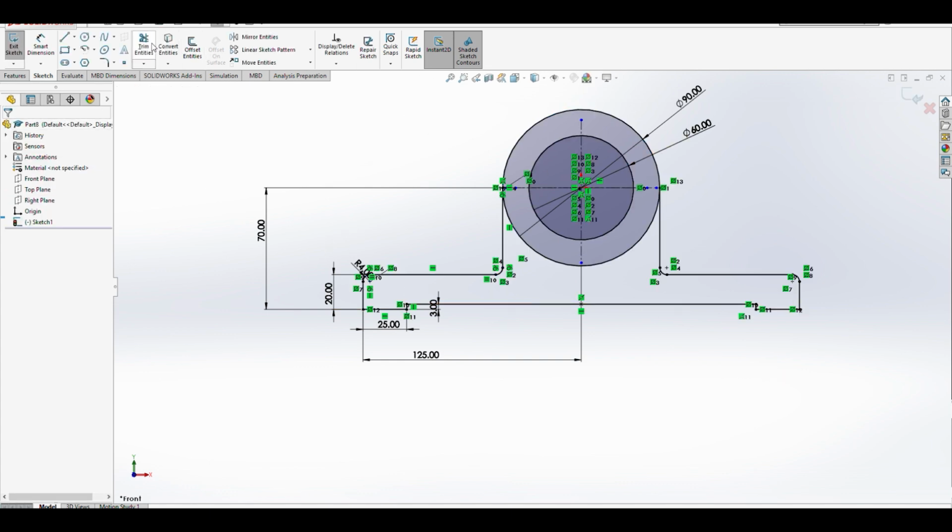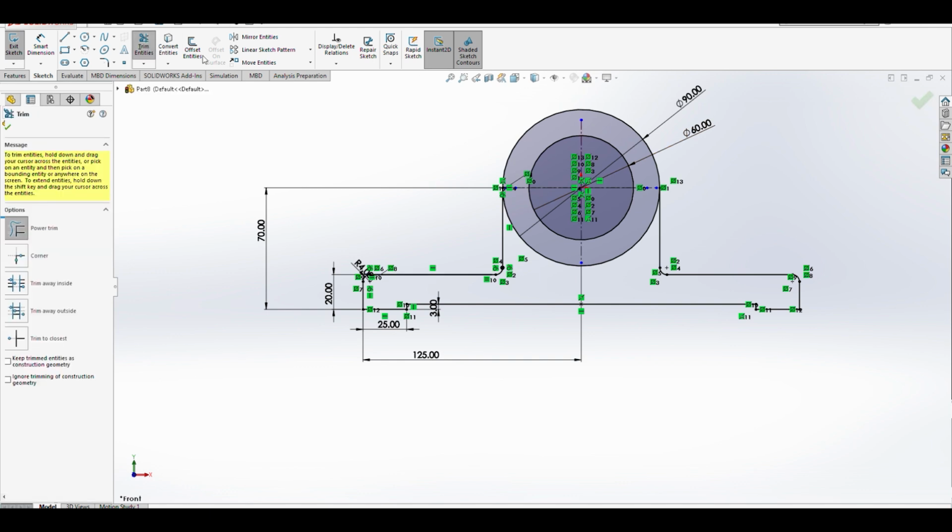So I'm going to go ahead and trim the entities. Now this is a brand new one. Okay, so see this little gray line? Anything that it touches, it's going to trim it up until the next intersection point. So I'm going to go ahead and pop that, and we don't have the rest of that circle to worry about. And the drawing looks like it's finished. Okay, so you can save that like your other ones. Save it as a JPEG if it's completely finished, or save it as a .SLDPRT if you need to work on it the next class.